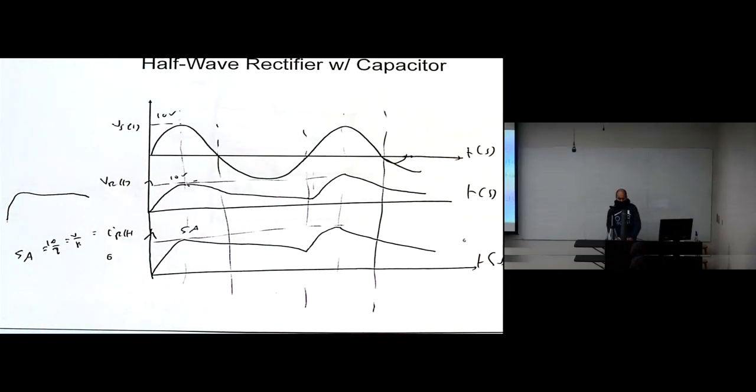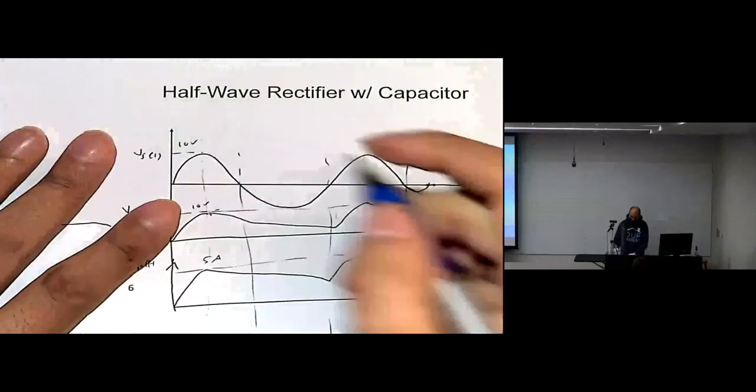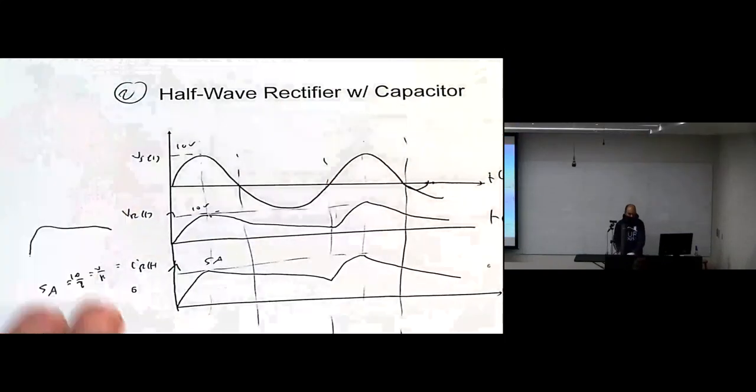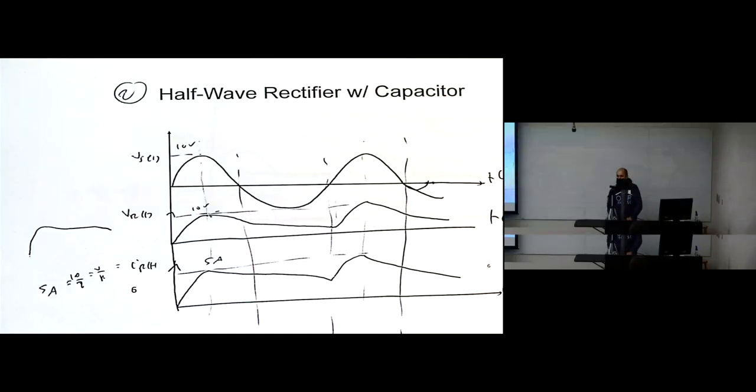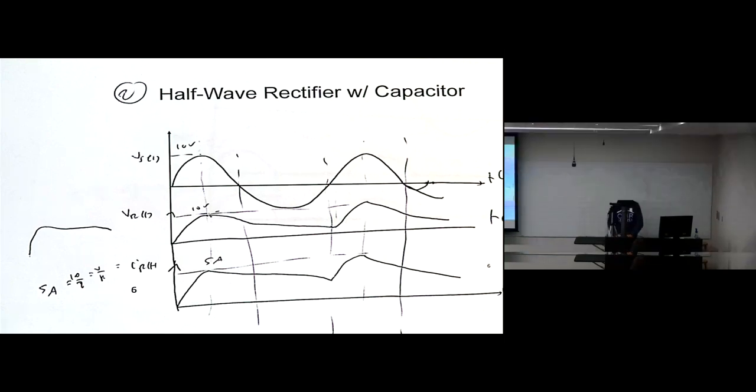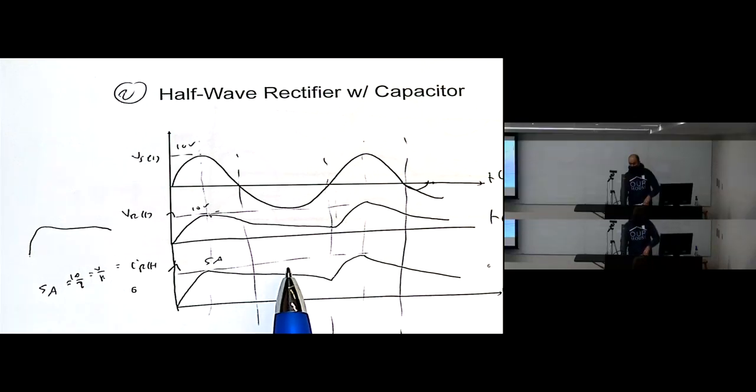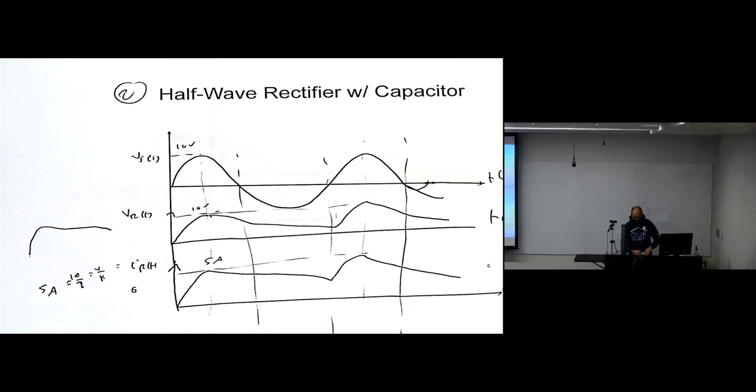Is that clear? So this is the other type of rectifier, which is half-wave rectifier type number 2. Half-wave with capacitor. So we have half-wave without capacitor, or the regular half-wave rectifier, then half-wave with capacitor. And we found that using the capacitor makes a big advantage. Clear? Now, what if we modify more? Can we make a better performance? Even adding the capacitor, sometimes I cannot make it like pure DC.